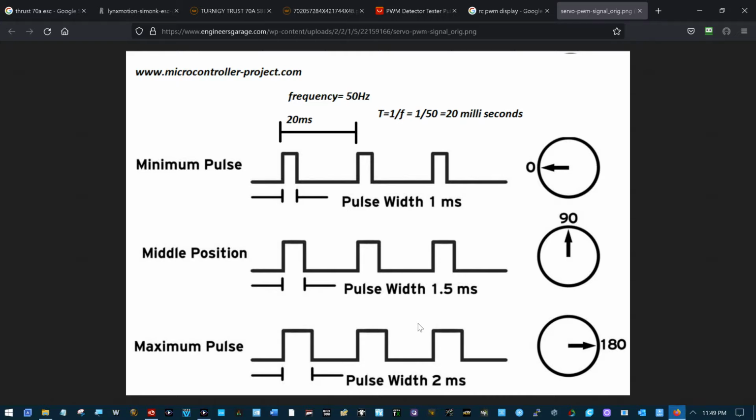You can buy a 100 ohm resistor with a tolerance of 20%. That 100 ohm resistor may actually be 80 ohms or 120 ohms. It can be as much as 20% out of tolerance for what it's marked and manufactured to be.